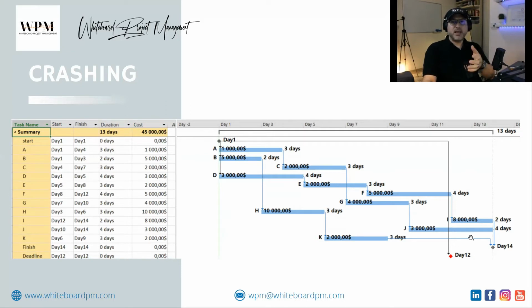You can say, yes, it's easy. I will take the longest activity here and I will shorten it by 2 days. This is not the correct way. The correct way is to make an analysis for the critical path and then decide which activity to be crashed. How? I will explain it now.